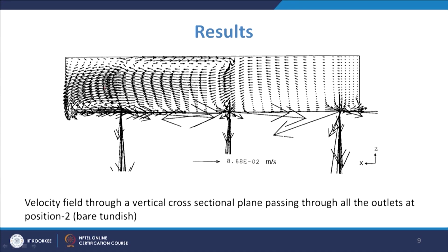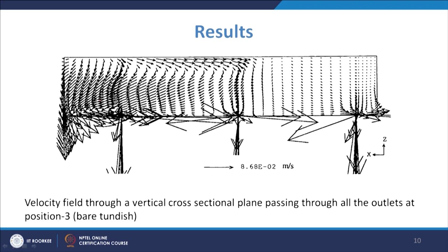As we move a little bit away from the wall to position 2, you see a type of loops also shown, and it is very evident that you have larger velocities in this zone, which is closer to the inlet plane. As you see further, the velocity near the inlet is quite high, and it becomes closer to the inlet plane along the length direction. So, you see that there will be changes in these velocity vectors. This you can draw.